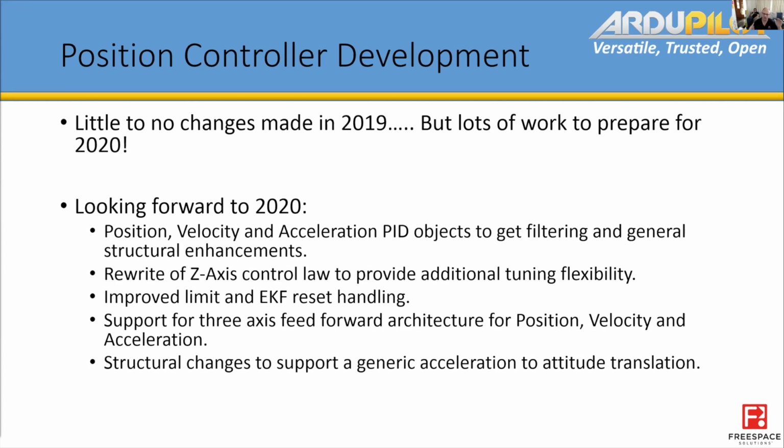Instead the aircraft just thinks it suddenly moved, and the attitude controller then slowly moves it back to its original target position, as opposed to getting this instant bang and this twitch and punch that we see go through the airframe.